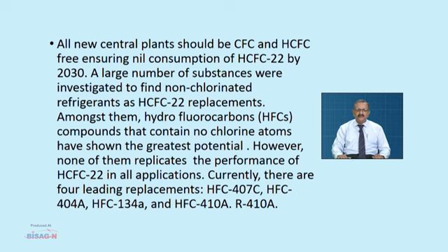A large number of substances were investigated to find non-chlorinated refrigerant replacements for HCFC 22. Amongst them, HFC compounds that have no chlorine atoms have shown the greatest potential. However, none of these items replicates the performance of HCFC 22 in all applications. Currently, there are four leading replacements: R407C, R404A, R134A and R410A.